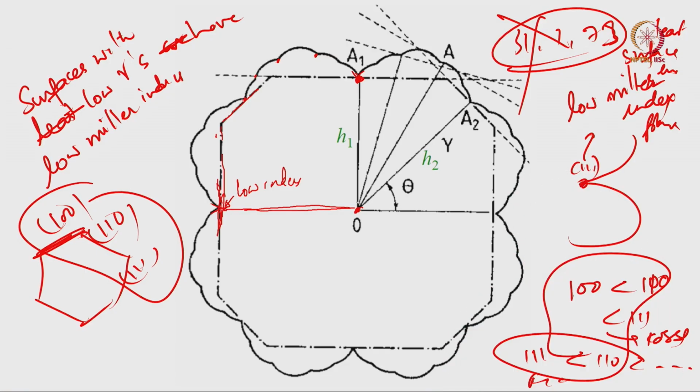So let us do the Wulff construction here. I have my stability points, and I am just going to draw my construction here. At this point I draw a perpendicular, at this point I am drawing a perpendicular, at this point I am drawing a perpendicular, like that I am drawing all sorts of perpendiculars, and I see that this is the trajectory that wins over all the other trajectories. So this is the envelope of all the trajectories. Okay. So the crystal shape that I get is here.